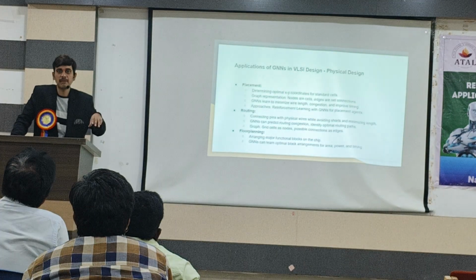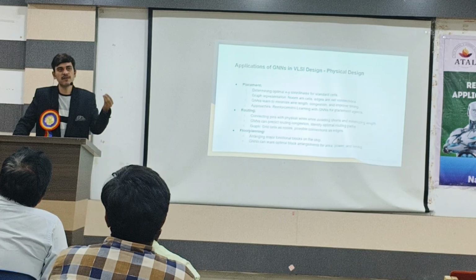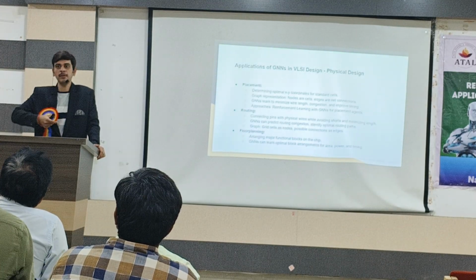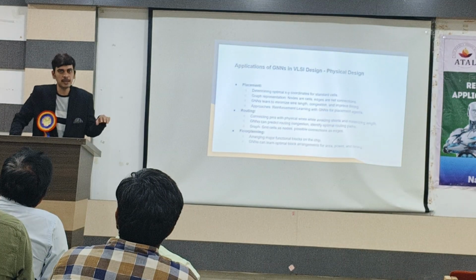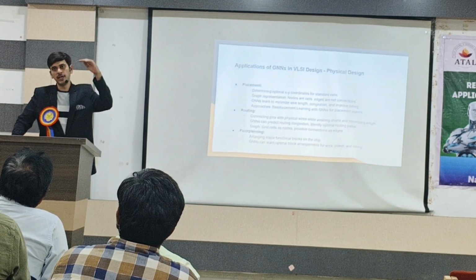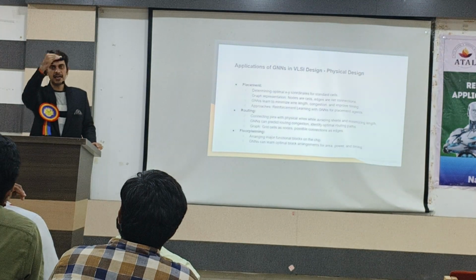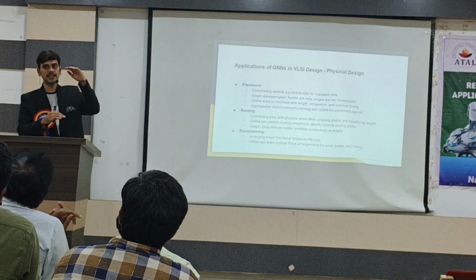We won't check the timing part for library issues, because some library issues are there, right? So library setup time will be there. In the timing report, if you see the Synopsys or Cadence timing reports, we have the input delay, the data path delay, and then the uncertainties and all these things you find in the timing report.